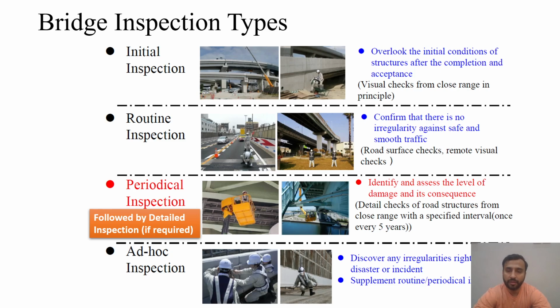In periodic inspection, it's more detailed as compared to the routine inspection. It involves a closer inspection. The bridge inspector goes closer to the different elements and gets an idea about the type of damages and its extent and the severity as well.